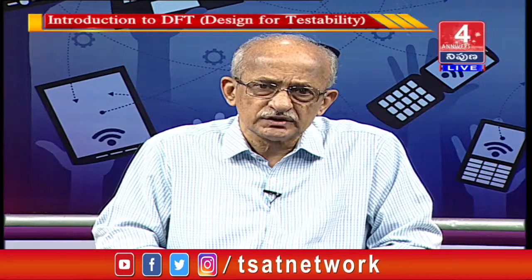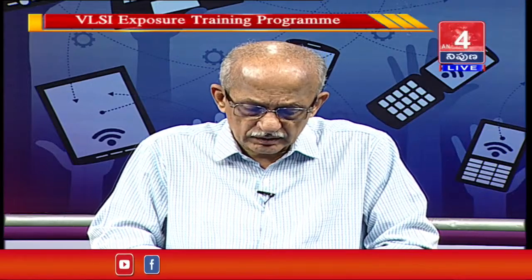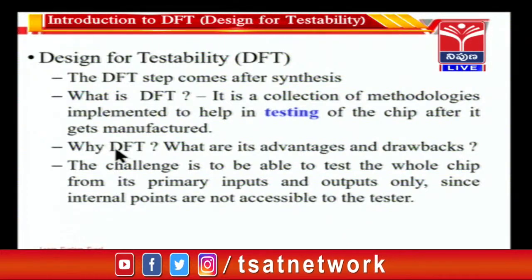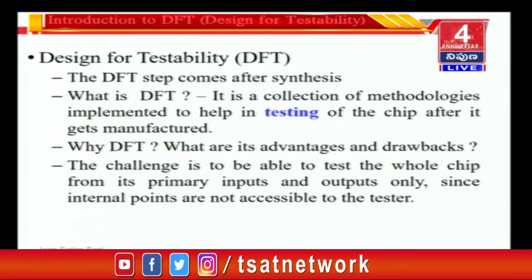If you have not covered a particular area to find out whether there is a fault somewhere in the silicon, then it is likely that if there is a fault in that area, it will go undetected to the user, and if the user then exercises that part of the chip in some of his applications, then the user will experience failure of that particular output, or failure of that particular chip. Therefore, the advantage is that it separates the good parts from the bad parts, and obviously only the good parts will be sent for packaging.